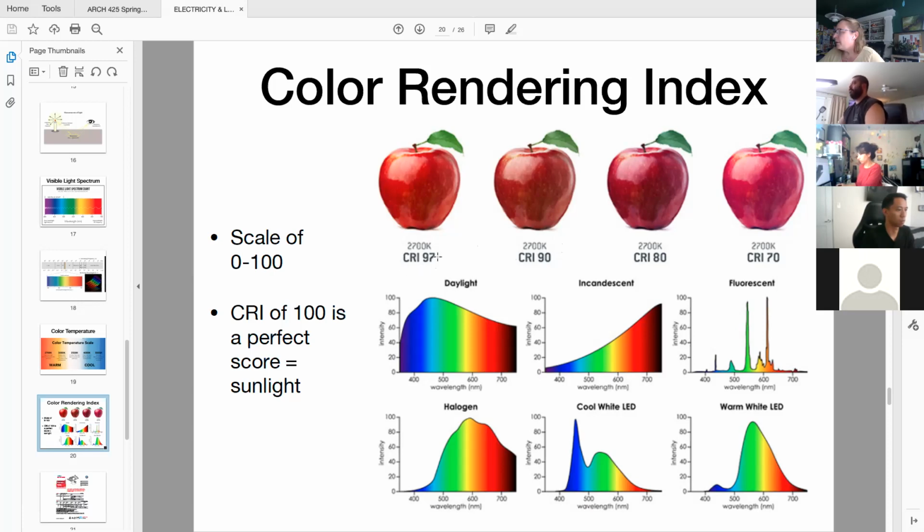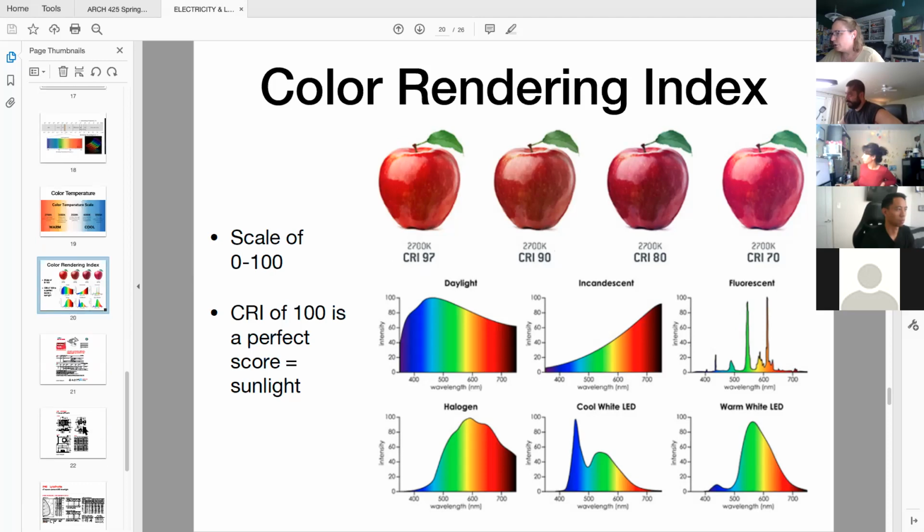If you go up to a CRI of 97, this will probably be exclusively used for extremely high-end application, such as a jewelry store case, possibly clothing stores, fairly high-end, but high-end retail or museum quality lighting is the only time I've ever really seen a CRI of 97 be required. CRI of 90, very good. Don't go less than 80. That's my 2 cents there.